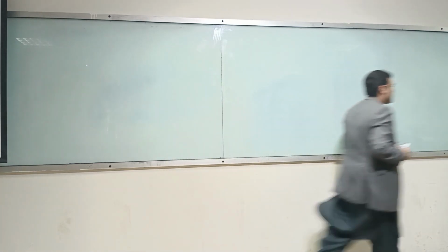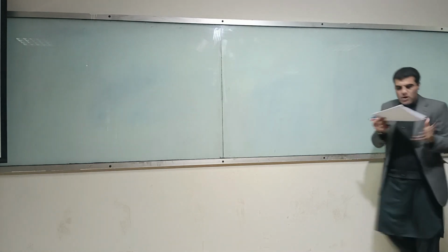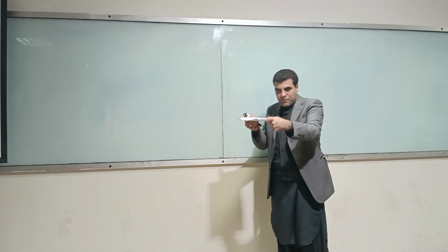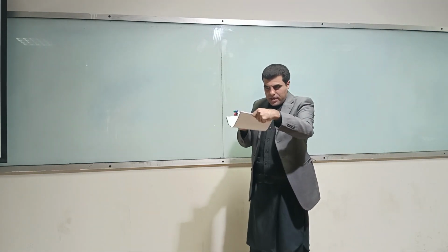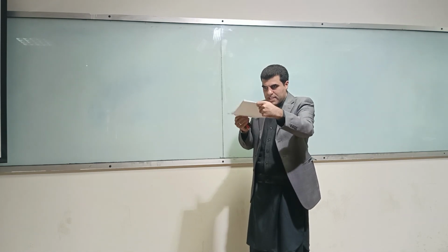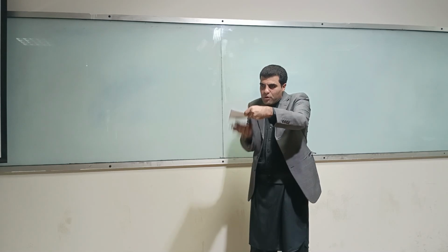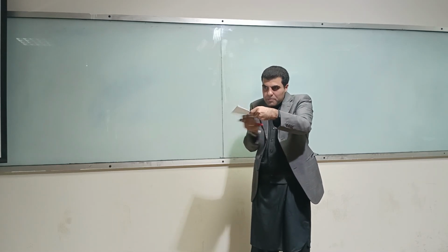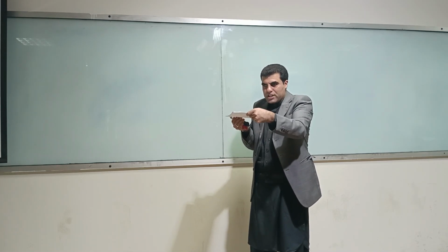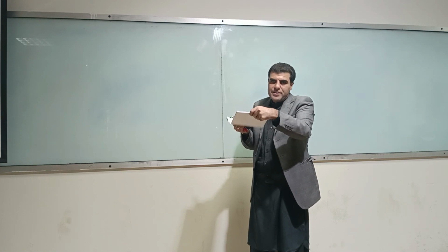What do I mean? If you have a very long slab, it can bend like this. So this means it is not stiff enough. So you provide some additional beams or columns to make it stronger, so that it doesn't bend. So you increase the stiffness of it.